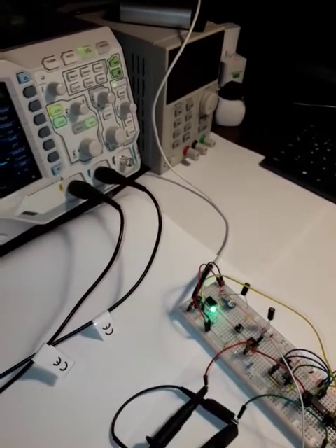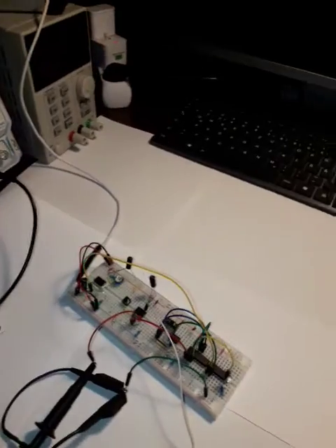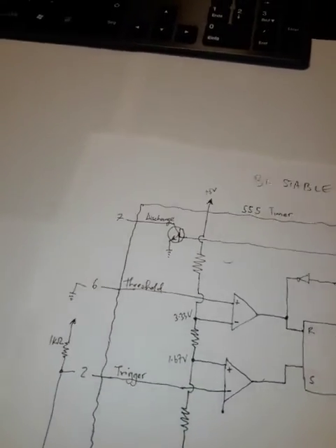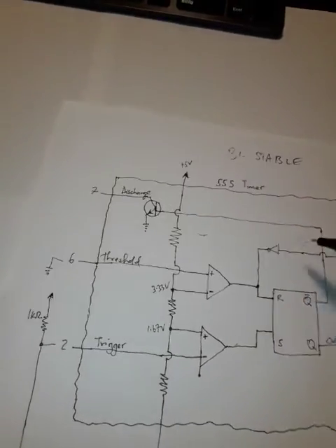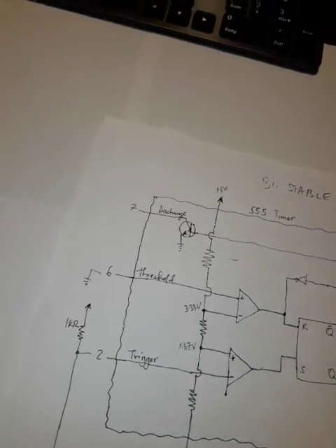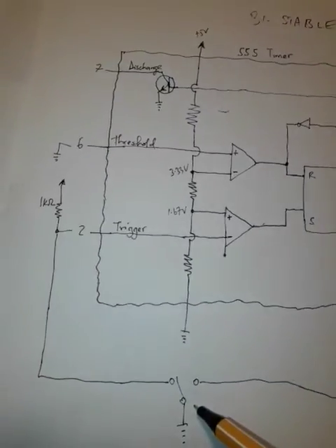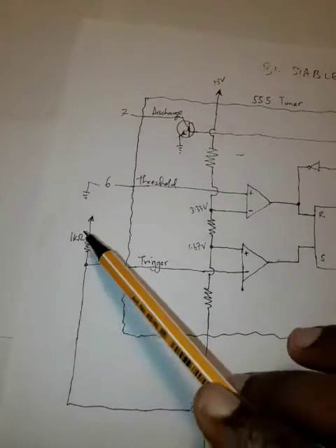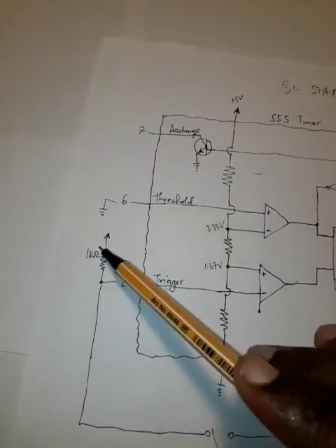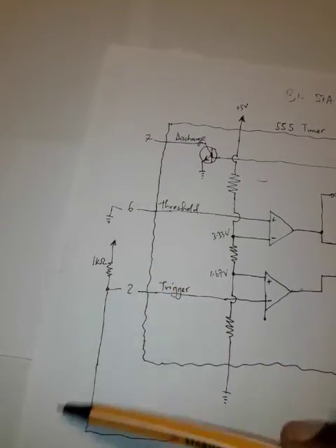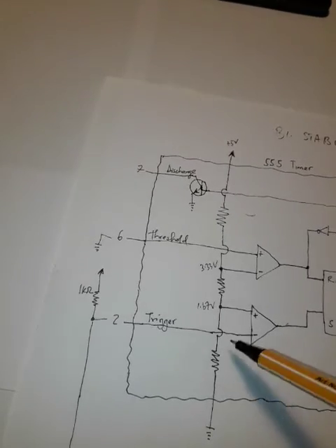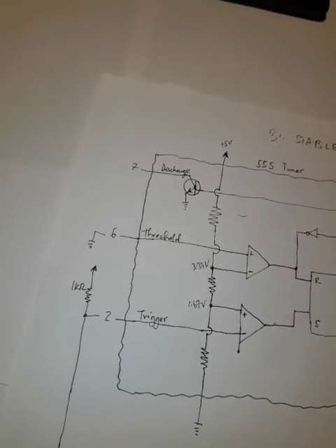And the last mode is the bistable. So in this case, I'm using the 555 timer as a switch. So I have a switch here, and once I push the switch to this side, this voltage goes to ground, and you have 0 volts here, and sets the latch. The latch stays high,